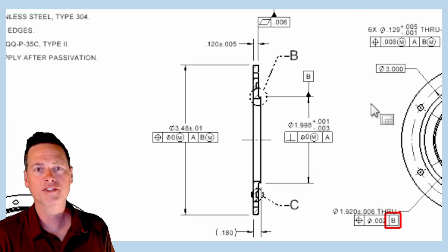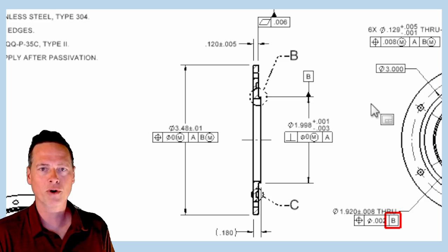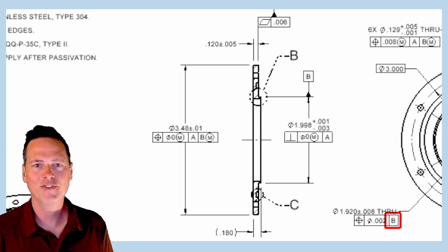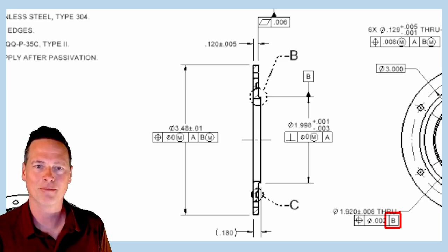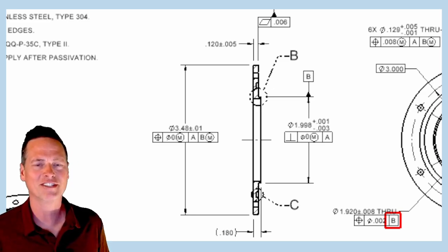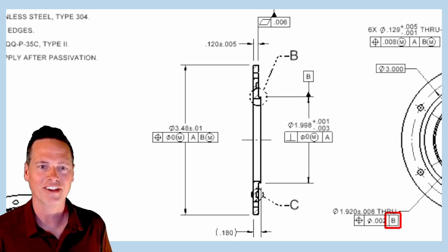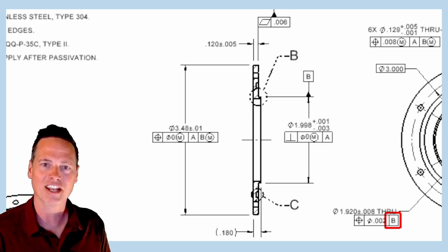You know, when a cylindrical feature is called out as a primary datum, that's a 4 degree of freedom constraint. This feature is just not long enough to establish that. It would be extremely difficult, I think, to find the natural orientation of this feature with a collet, without just loading it up against the datum A feature.